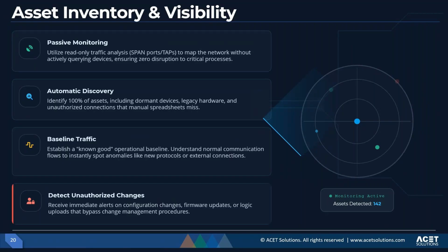Passive monitoring, continuous discovery, traffic baselining, and real-time change detection convert a black box OT network into an observable system. So misconfigurations, vendor surprises, and adversary actions are caught before they become safety and production incidents. If we talk about passive monitoring, modern security programs rely heavily on it. These tools observe network traffic without generating active probes, ensuring there is no risk of disrupting fragile PLCs,